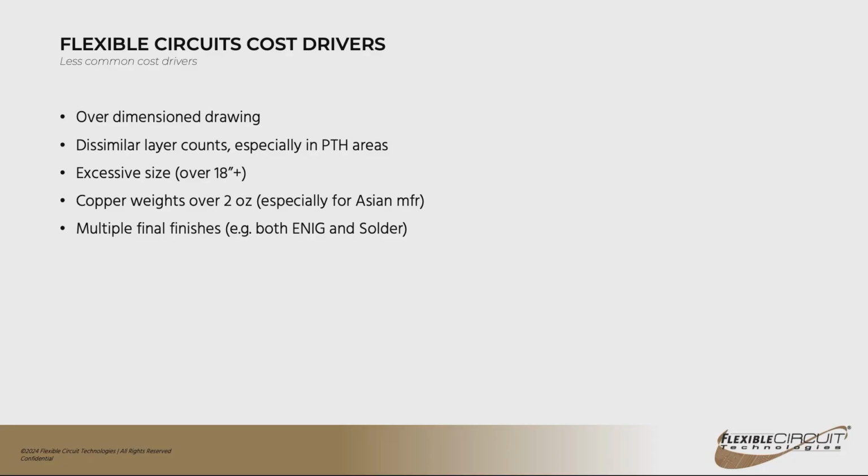But their allowance, if the flex is not inserted perfectly into the connector when it's clamped down, you can actually damage the conductors. And a lot of times that damage will be just a crack that will not show up until the device is actually out in the field. So just something to be aware of when you're doing your design. I prefer to go to the single row if you can use those and stay away from the dual row.